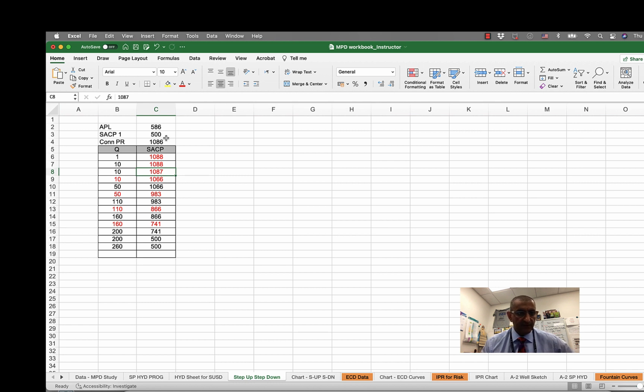And I believe, if I'm not mistaken, because we were doing a 6 1/8 inch hole, the flow rate here is 260 GPM. You can see that, and you can see this is when you were drilling. This is while you are drilling, and this is when the pumps are completely off.